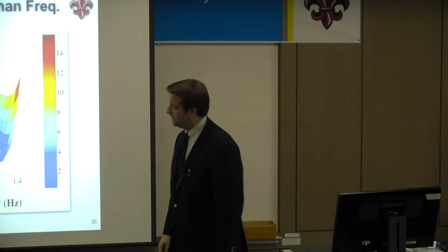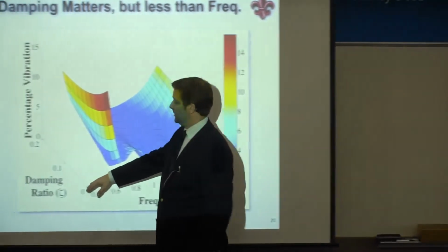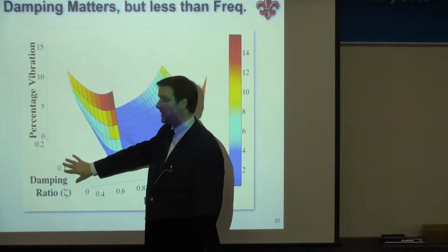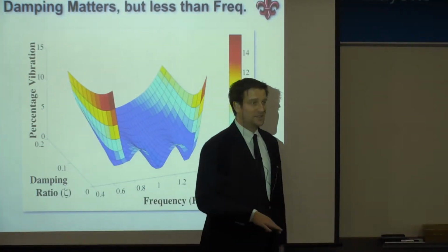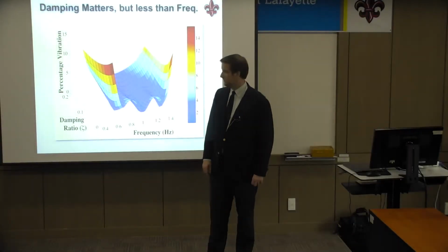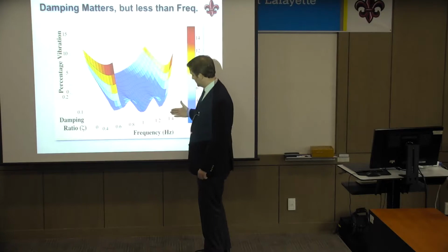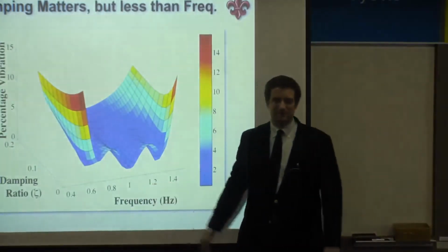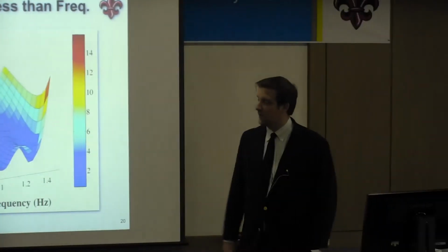We also can look at sensitivity to damping ratio. The reason we don't talk about this so much is that these shapers are much, much less sensitive to damping ratio than they are to natural frequency, errors in natural frequency. So we almost always just stay on this axis. So we're not so sensitive to errors in damping ratio.